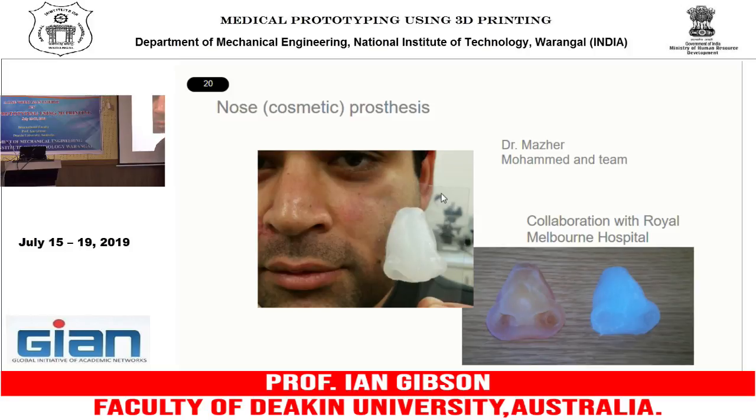And what you can also do is you could model the cartilage inside the nose, so that would be more rigid. And so you can do a lot of very interesting and precise anatomically correct models. It's a photopolymer. It's basically an acrylate of some kind. So yeah, it's UV cured, but what happens is that the curing process results in a different shore hardness depending on the mixture. For the Connex machine, it has 3 print heads. So they can be either a mixture of colors, so you could make a color part, or a mixture of materials, so you could make the soft and hard parts.